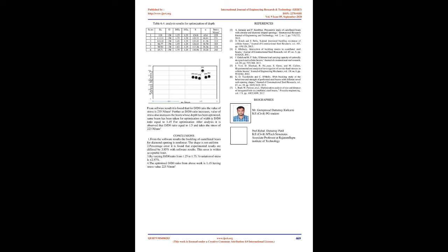Fabrication of castellated beam. Castellated beam has been derived from the I-beam having depth 100 mm. The diamond pattern has been created by using machine, i.e. profile cutter. For that, first the detailed drawing has been made. In case of profile cutting, cutting profile has to be drawn on software with the real scale. Cut profile for cutting diamond opening.